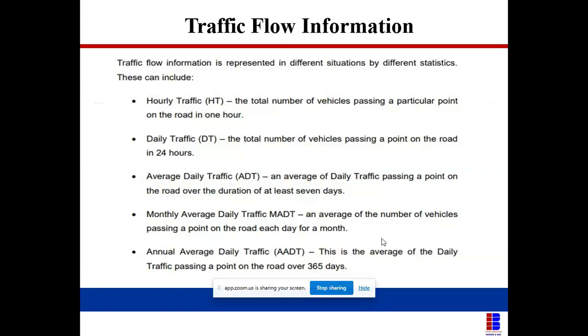So with this daily traffic, if I'm designing a rural road for which they've specified and carried out analysis, and it is a road that has more traffic coming on it, I'll be looking at making my road width more. If the traffic volume is less, my road will be narrower. That's why I say most times on our rural roads, our village roads, the width of the carriageway is not more than 6 meters, because the traffic flying that road may be like 100 vehicles per day, 6 meters, some 5 meters, because the traffic volume is less compared to the urban areas.